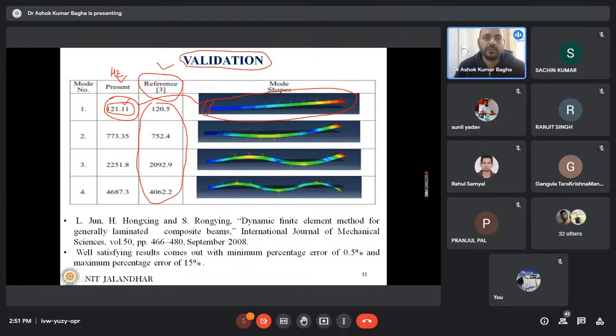It is fixed from here. And you will see that the beam is vibrating like this. So it means that during the first fundamental mode, all the mass of the beam either moves in the plus direction, let us say this is the plus direction, or it moves in the minus direction, right? And you will see during the first mode there is no nodal point here. A nodal point is a point where the response of the structure is approximately 0.